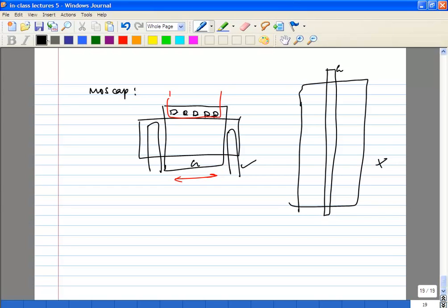What else? The other things I think, transistors. We already looked at splitting transistors into fingers and so on. But the one thing to remember is splitting into fingers can also be useful. Even for the capacitor, right? Instead of having one large capacitor or one large transistor, splitting into more devices can help in other ways. Let's take the case of the bias. Bias transistors are typically much larger than the signal transistor. It helps you to actually